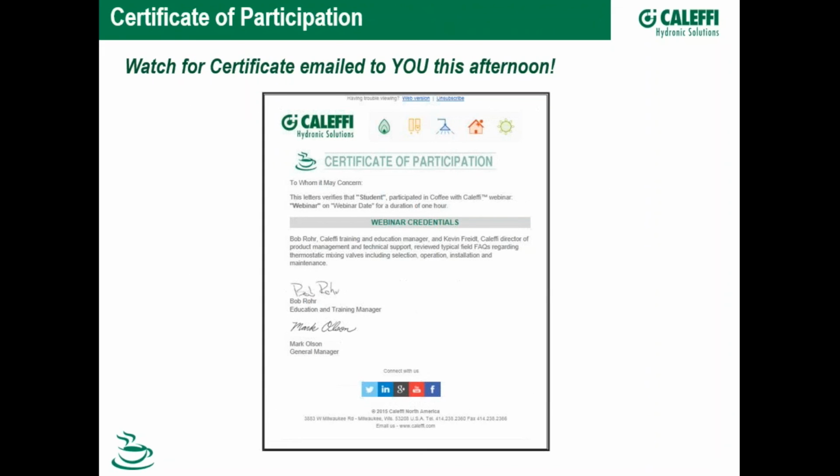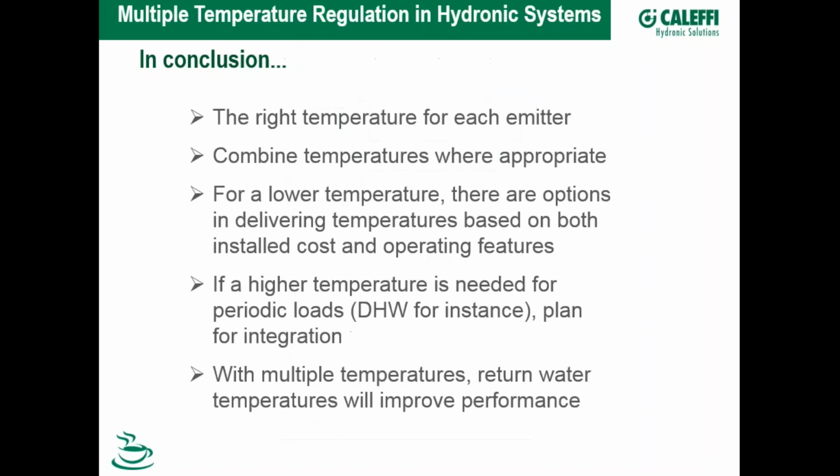One thing, if I could add, is a lot of the new boilers have multiple mixing potential right in the control on board the boiler, so that does take some of the cost out of it. And I think some of them now actually have multiple outdoor reset curves available too. So look into that when you're shopping for your boiler. You might have the equipment you need to do these multiple temperatures already on board the control there.